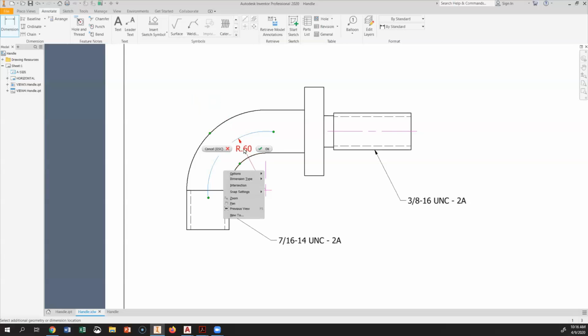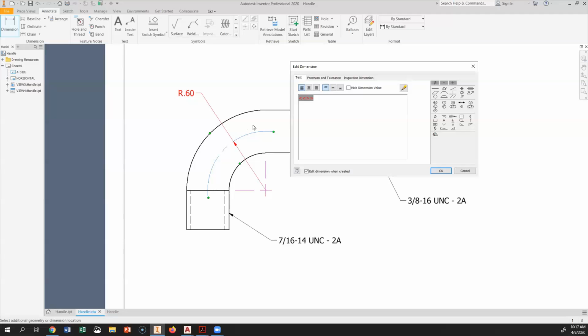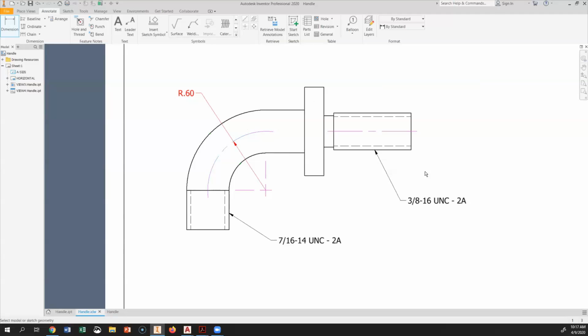Try to do right click and select this option, arrowhead inside. So that gives you this nice illustration here, everything, they don't run to each other, and also it gives you the center line. So that means that this is the one that helped us to create this arc. So it would be helpful to say, okay, all these bend centers where it is.